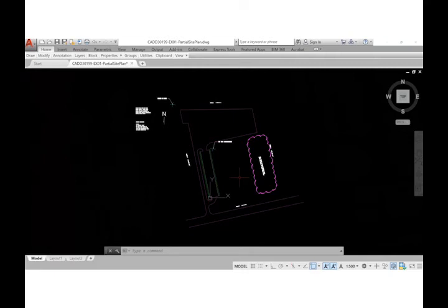The next thing is that you, know, write it down. You want to maybe save it as a different file name and delete all the other files, or place them in a layer that you can turn off, or maybe even freeze. You don't want to bring in too much information in Revit. That will slow your Revit computing. Slow down your computer.